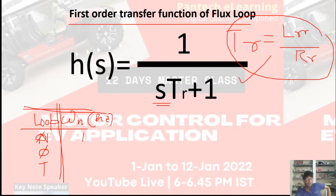The natural frequency of the speed loop is 1 Hertz, and the flux loop is 10 times faster than that, 10 Hertz. Torque loop is the fastest loop in motor control, which is 100 Hertz.